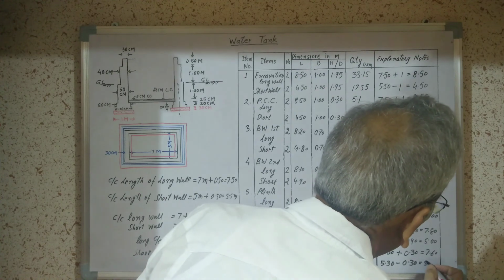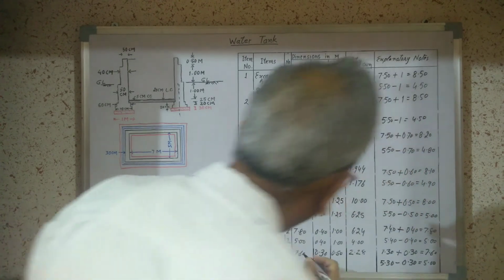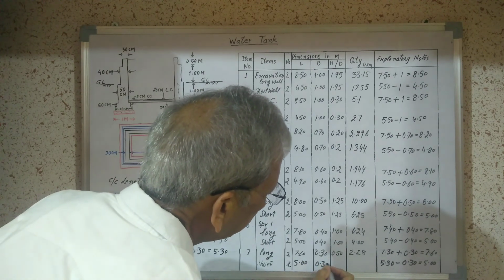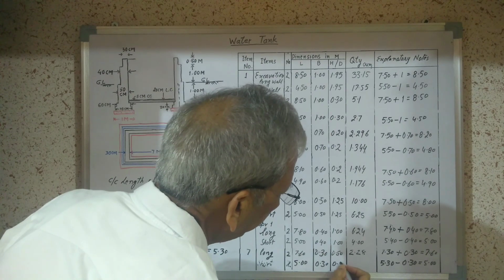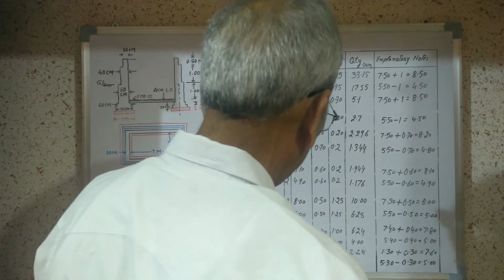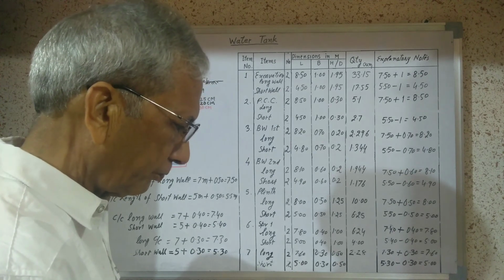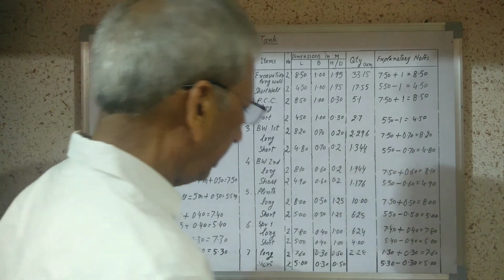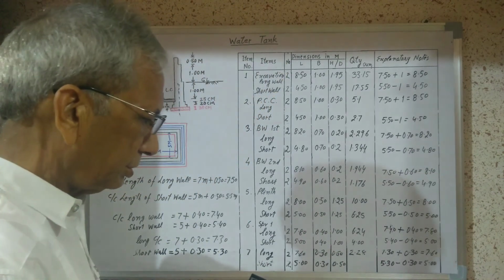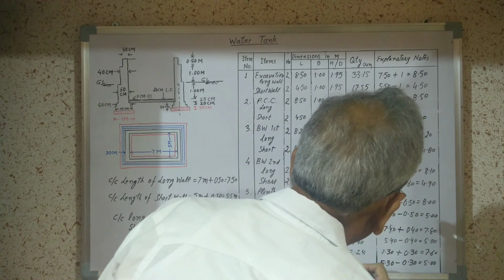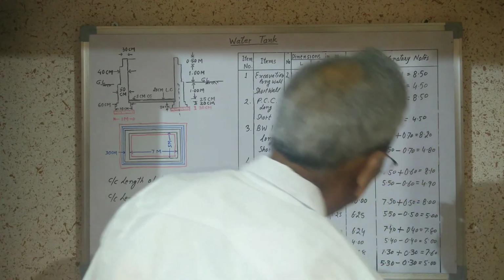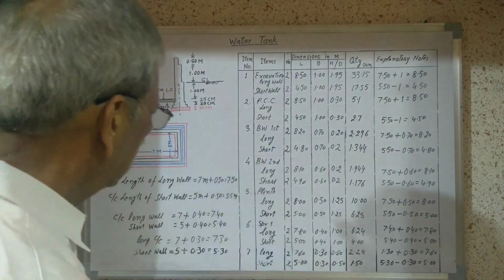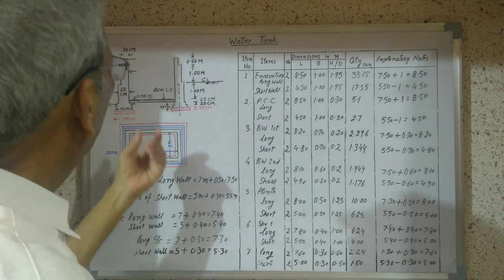It is equal to 5 meter. We will take here 5 meter. Width will remain the same, 30 centimeter. Height will remain the same, 50 centimeter. Now the total will be 2 multiplied by 5 multiplied by 0.3 and multiplied by 0.5. It is 1.50 cubic meter. These are the calculations of all these components of a water tank.